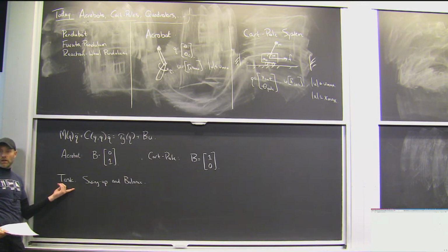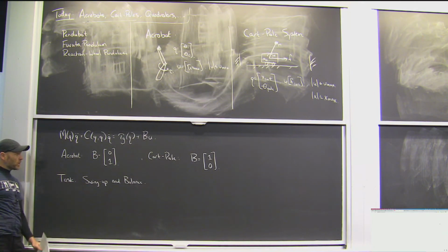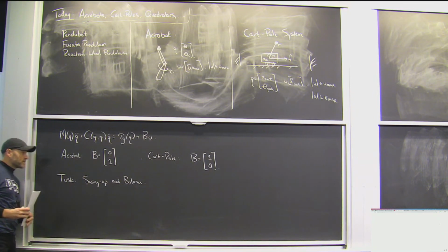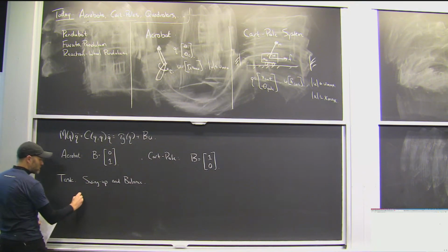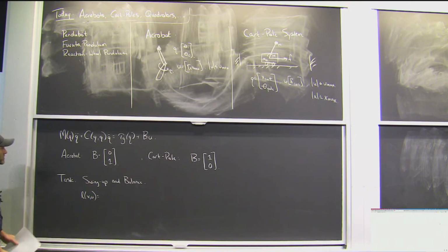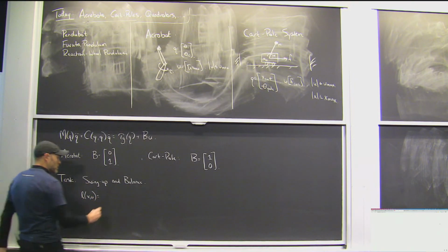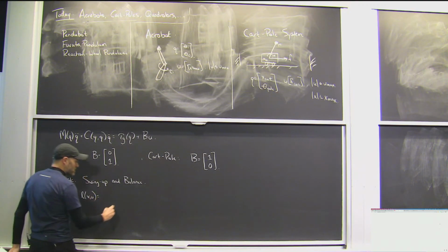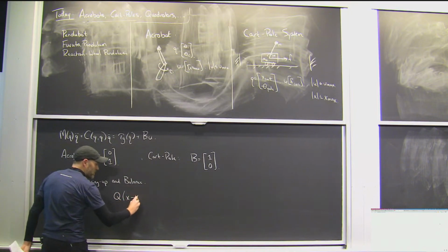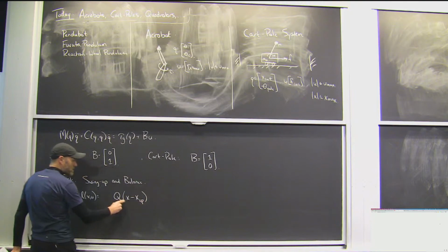Okay. We can write that in various different cost functions using the language of optimal control. In fact, the cost function we used for LQR would already be enough to be interesting for this. If we said that our instantaneous cost was just some quadratic cost which said that I want to be close to the upright. So I'll write my same quadratic form, but this time I'm going to take the difference between my current state and the upright state, and I'll use that as my quadratic form.